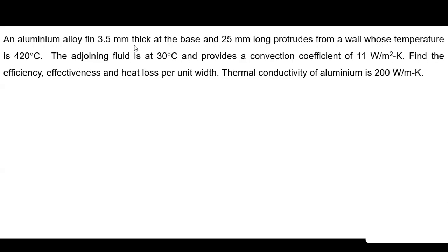The thickness of the pin is given, 3.5 millimeter at the base, and the length is also known. 25 millimeter is not too long. The thermal conductivity of aluminum is 200 watt per meter Kelvin. With this information, as the length is not too big, only 25 millimeter, we can assume that this is a fin with insulated tip, and we can solve this problem.